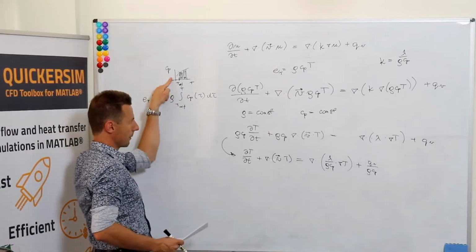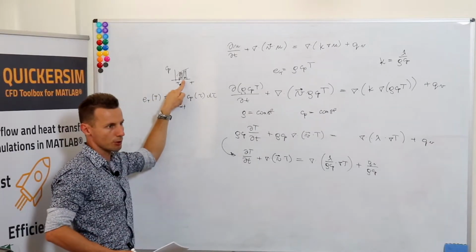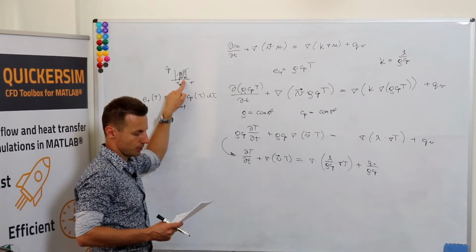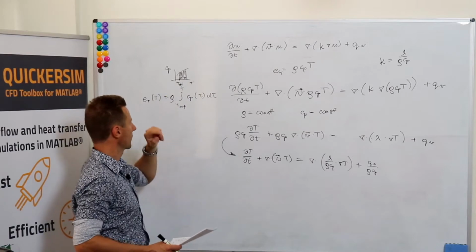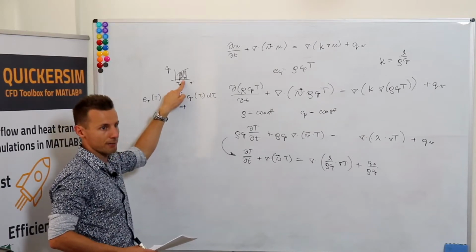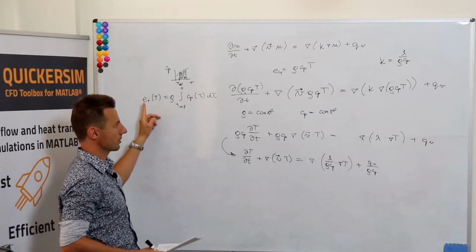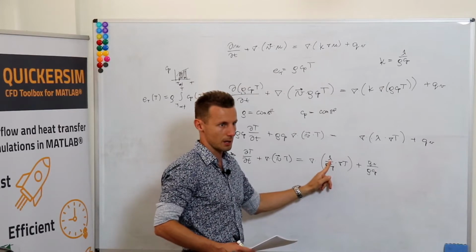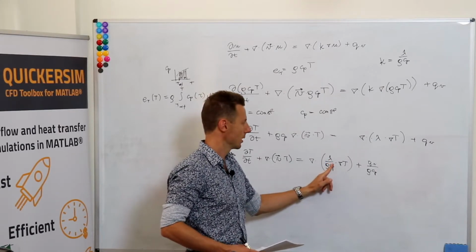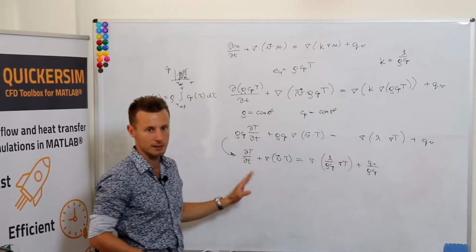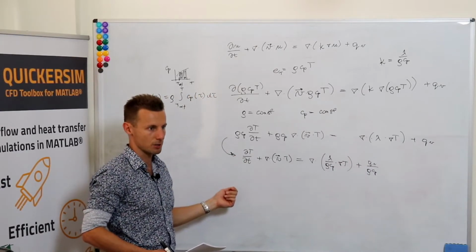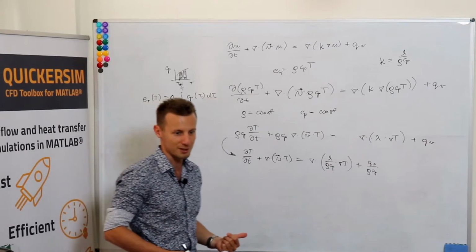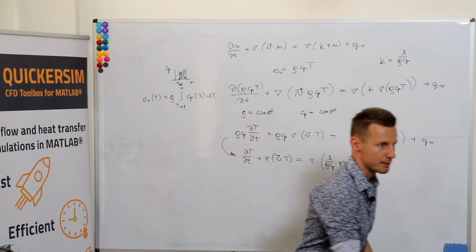Why do I mention that? I mention that because this already introduces nonlinearity into the system. So very, very often, if you're having cases like that, and you might often have cases like that, the Cp may change with temperature, your lambda may change with temperature, then it's really much, much better to not make any simplifications like that, but to always stick to the conservation law, and you know that not temperature is conserved in physics, but the energy is conserved in physics.